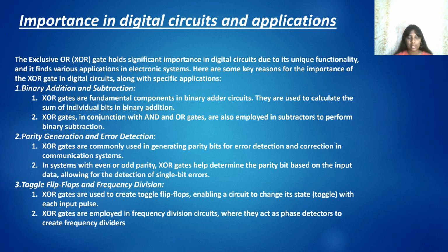XOR gates, in conjunction with AND and OR gates, are also employed in subtractors to perform binary subtraction. Parity generation and error detection: XOR gates are commonly used in generating parity bits for error detection and correction in communication systems. In systems with even or odd parity, XOR gates help determine the parity bit based on the input data, allowing for the detection of single bit error.